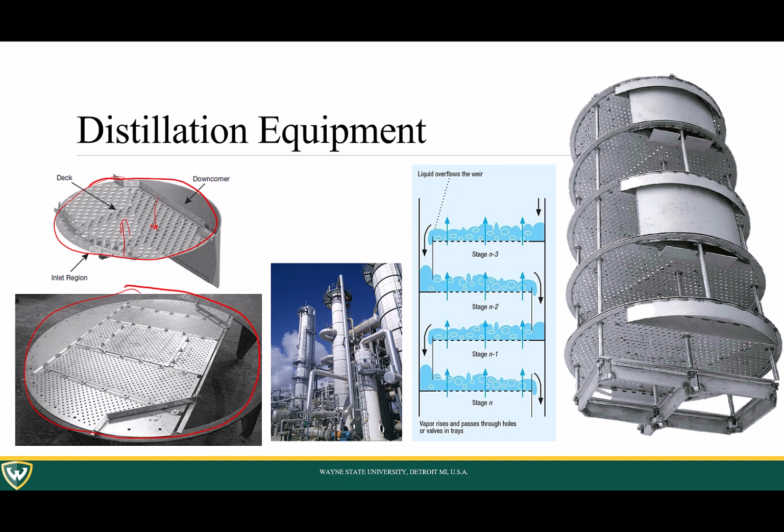That's another thing I want to point out that's important. The vapor leaving this tray and the liquid leaving that tray are in equilibrium with each other. The vapor coming into this and the liquid coming down do not really have a relationship together. Okay? It's only the vapor leaving and the liquid leaving the trays that are in equilibrium with each other, and where you can get the components of those from the vapor-liquid equilibrium diagram.